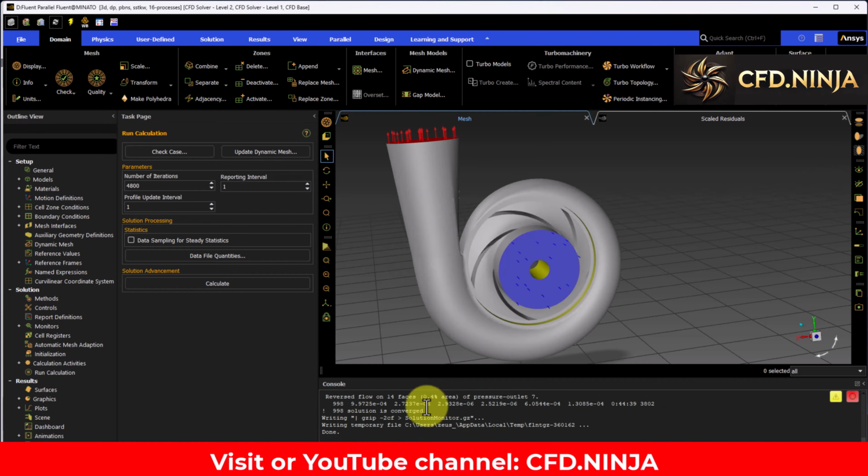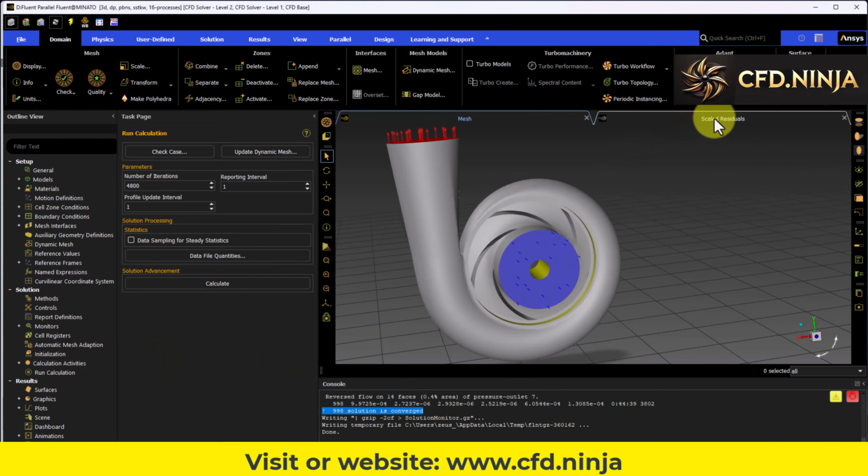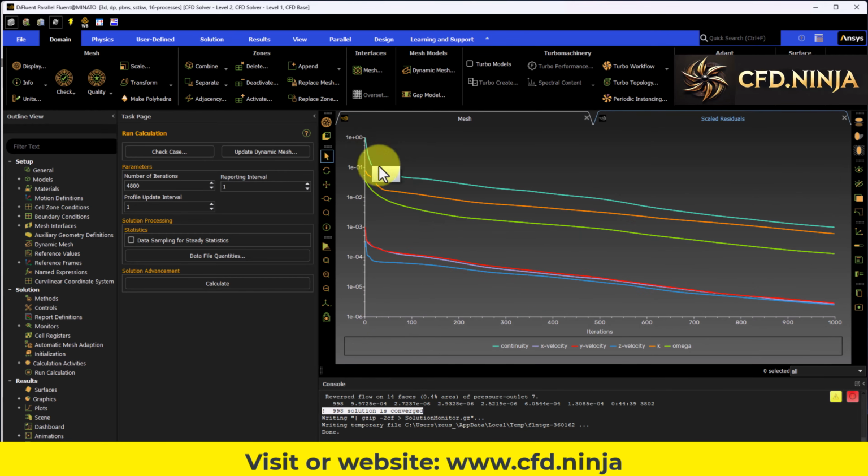Visualize in which iteration it reached convergence. In this case it was in 998. Very good. We can visualize the results here. Let's see, wait a moment here, scale of residuals. You can see that the convergence has been continuous, constant, and largely thanks to the mesh. Also the configurations that we have developed.